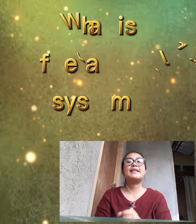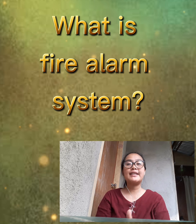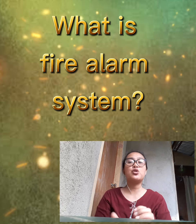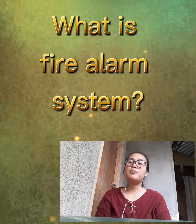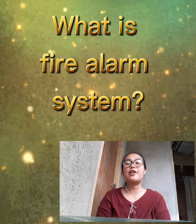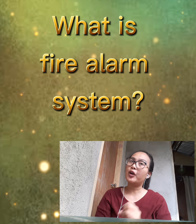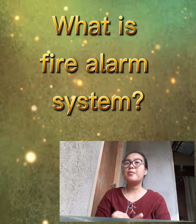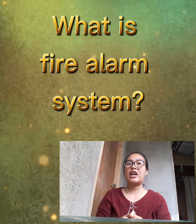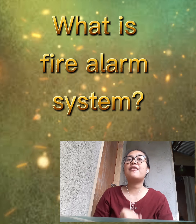The fire alarm system. What is a fire alarm system? A fire alarm system has a number of devices working together to detect and warn people through visual and audio appliances when smoke, fire, carbon monoxide, or other emergencies are present. Most fire alarm systems are made up of a fire alarm control panel, primary and backup power supply, alarm initiating devices, alarm notification devices, remote control and display panels, and the building safety interface.